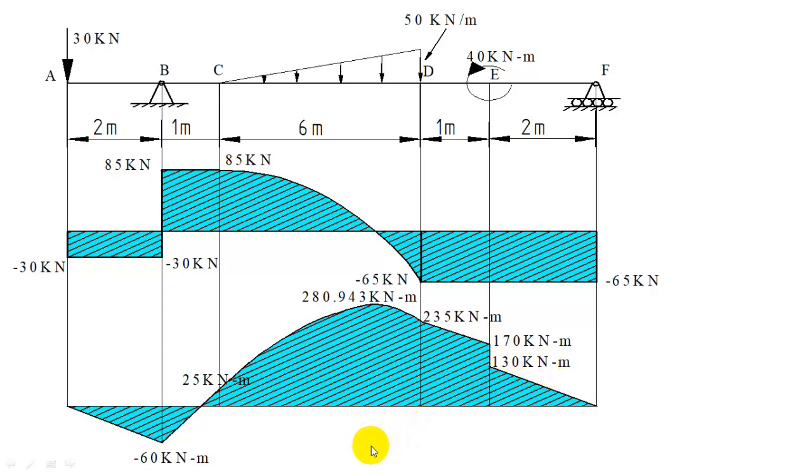Now you got the bending moment curve. So all these variations are linear, except here under UVL you have got a cubic variation with a peak. So all this has become complicated because shear force has come to 0 under this UVL. If the shear force is not changing its sign, then you could have easily plotted without calculating this location and without calculating this peak. You could have continuously plotted increasing this to that right end.